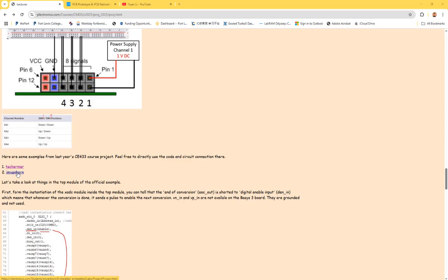So remember last time we were talking about why we have to skip 8 data points? And I was thinking about having a data latch in the middle. Right, here's the ADC. Analog input, we got data here. So the name of the output is actually data, right? So it's a wire input in the top. And you have your SPI. SPI also has a data, it's an 8-bit bus. So in the middle, if you have a latch, I call it a data latch.